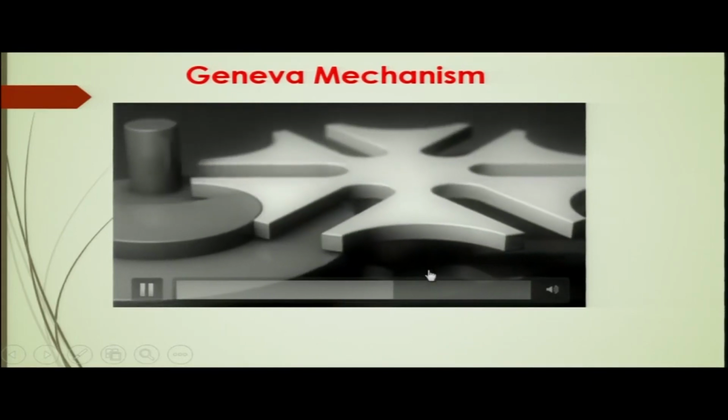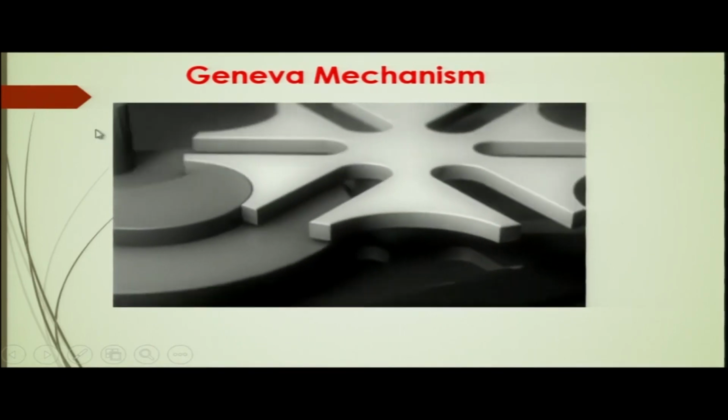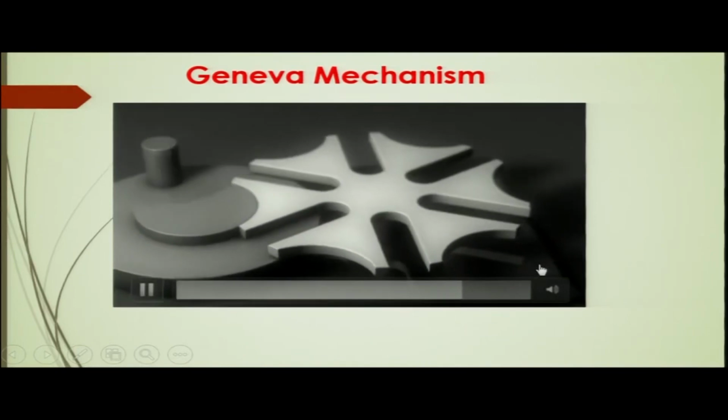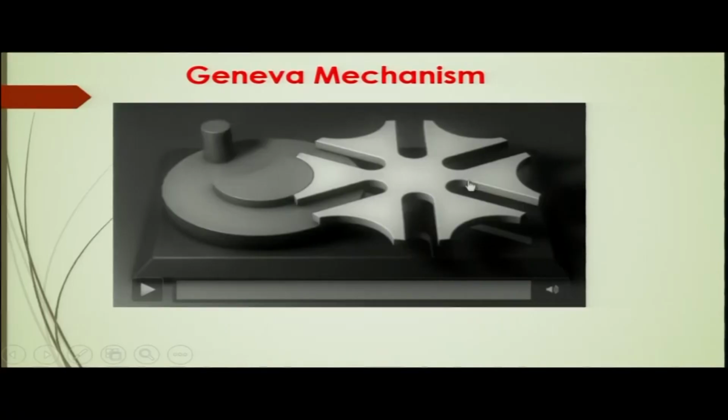So, the load of the sub assembly will be on this Geneva wheel, and with this load this pin has to be able to move that much load from one position to another position. Okay. So, the pin becomes the weaker point. If for any reason the pin breaks, the mechanism collapses and it cannot work, as you understand. That is the first drawback of the Geneva mechanism.